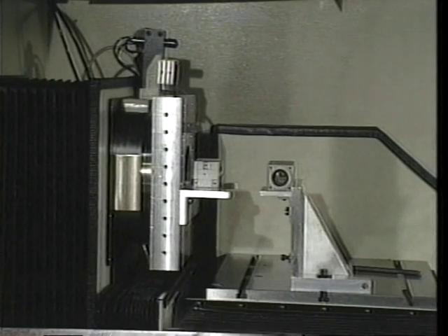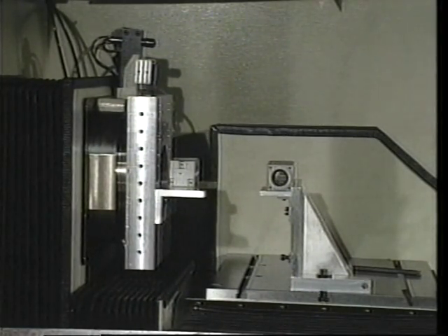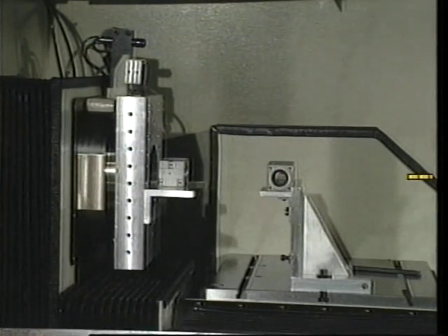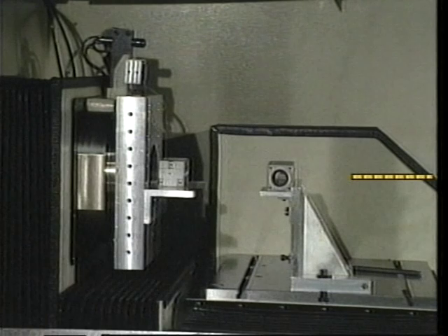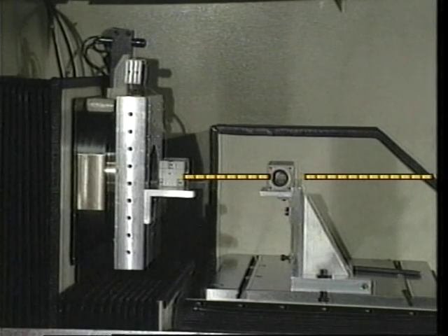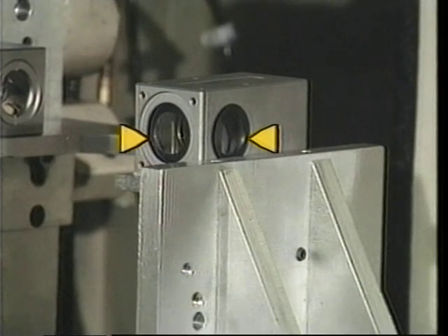In this measurement, the reflector will move with the z-axis slide and the interferometer will remain stationary on the x-axis slide. As you recall from an earlier lab, the laser beam enters the interferometer first. Therefore, with respect to the beam path, the interferometer must lie between the laser and the reflector. Note that two ports are provided on the interferometer to allow inline or right angle measurements.